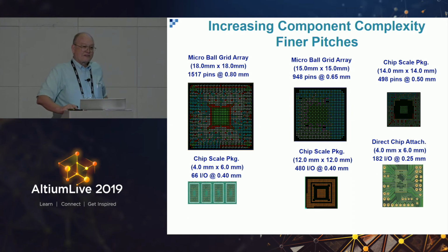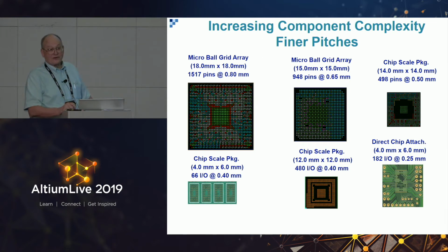The semiconductor industry said, because of mobile phones and automobiles, we're only going to make one package. It's going to be the small one. We're not going to make a big package just for you. And the other thing that caused was they wanted them to be tin lead. And they said, no, since the mobile phones are lead-free, the packages have to be lead-free, which forces the military to reball all of their components with tin lead connections that they're still allowed to use, and not the lead-free ones. So this will continue to go on.